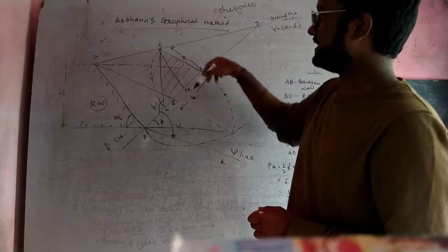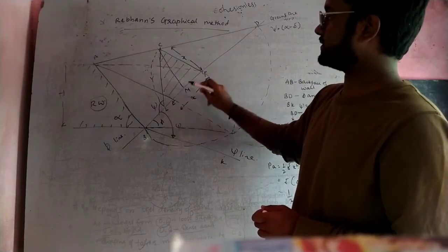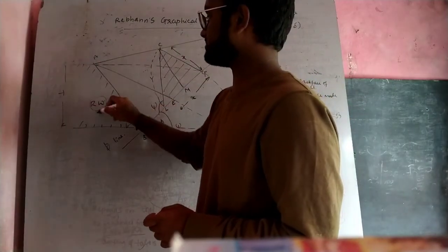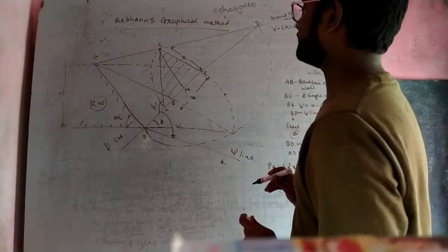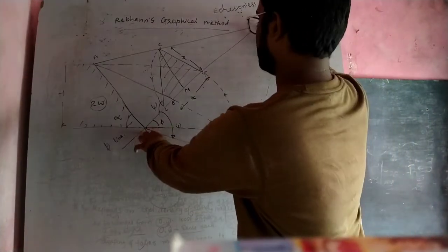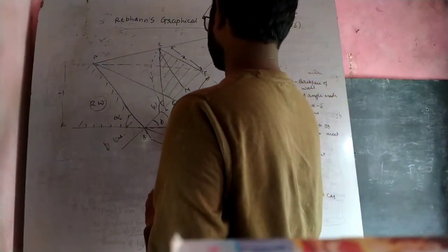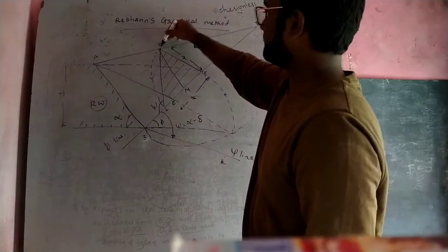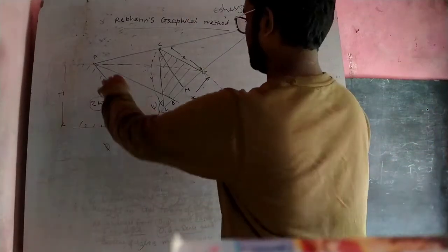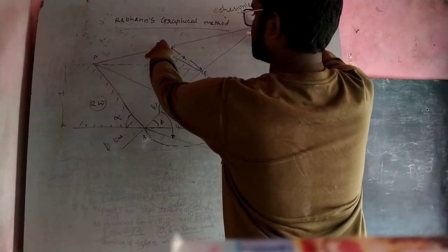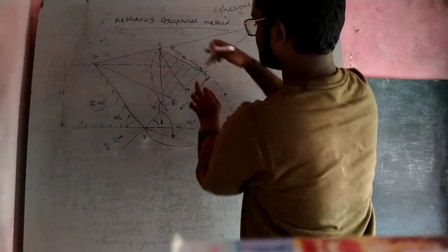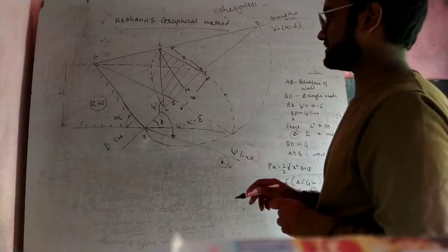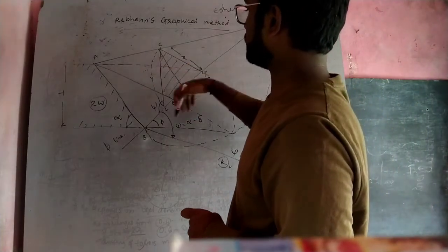There is a perpendicular drawn which is perpendicular to LG, that is line CM is perpendicular to LG. This AB is the back face of the retaining wall. With respect to BD, we have to make the phi angle. B and D make the phi angle. Psi is equal to alpha minus delta, that is what we have done. We have erected the perpendicular CM. A and D should meet at C with this perpendicular erection, that is CM. We have got the psi line, we have got K, that is the active earth pressure constant. So this is what we have got.